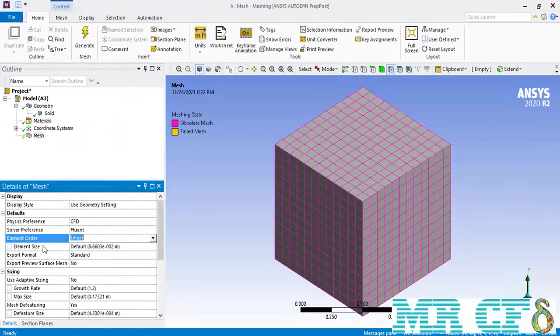It should only be pointed out that when you define the element size here, that does not necessarily mean that the size of each element is precisely equal to this value, but this means that the size of each element is less or equal to this value. For example, in order to calculate the length between 2 nodes of an element, we select the element selecting command and then select 2 elements that are placed next to each other.